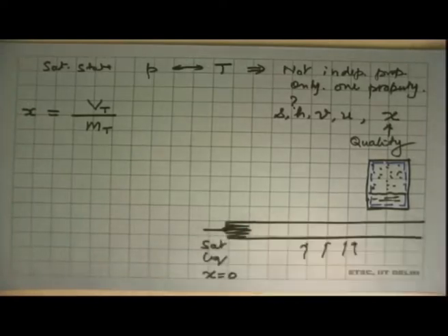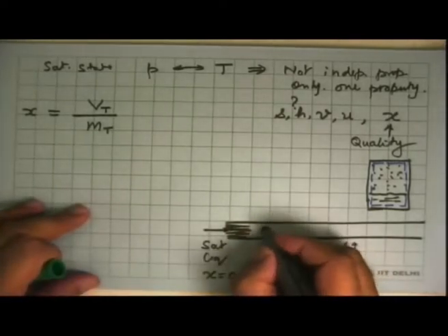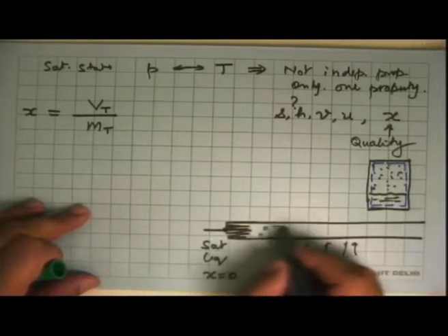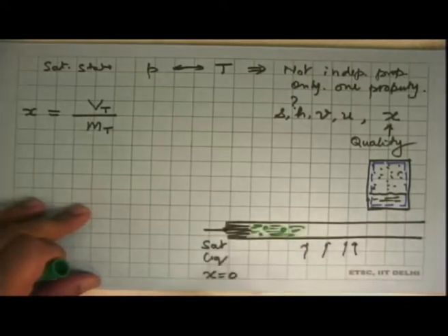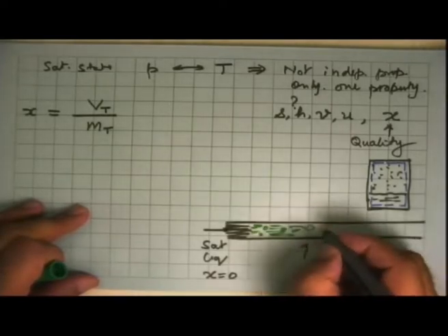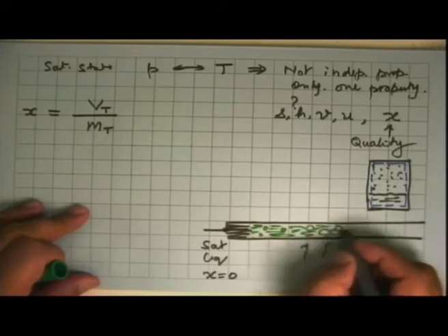What happens to this liquid as it gets heated and it flows through it? So as some heat is added, it forms small vapor bubbles which are largely floating in saturated liquid. As more heat is given, these bubbles become bigger and they still surround the liquid.